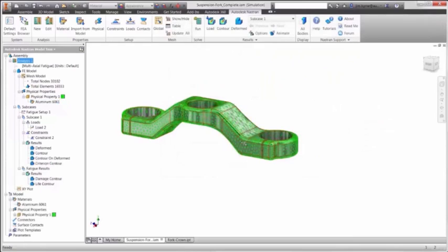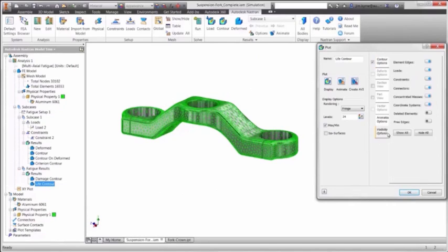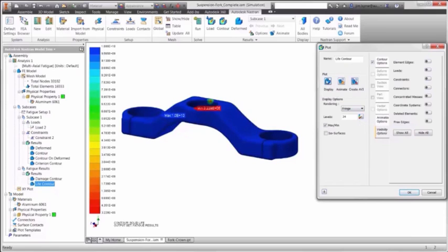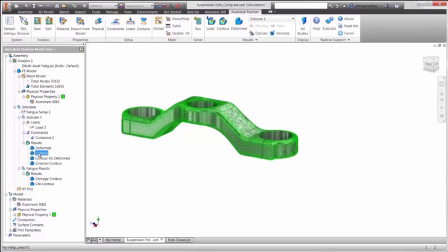We can now look at the life plot and find out how many 5,000 Newton loads the fork crown will handle before cracks begin to form and ultimately cause the part to break. We can see here that the number of load cycles is 322,000, with a very large applied load. We can consider the part to be safe for normal use.